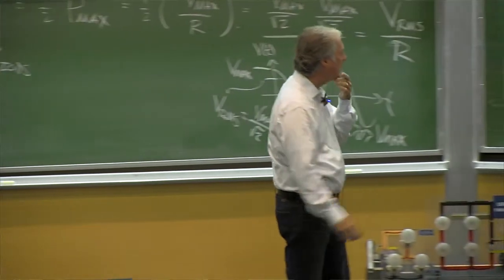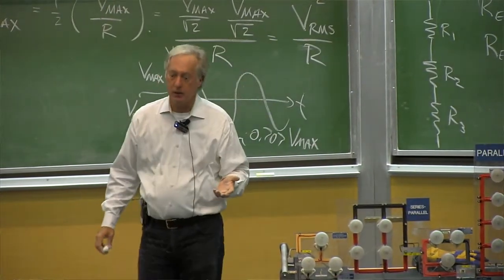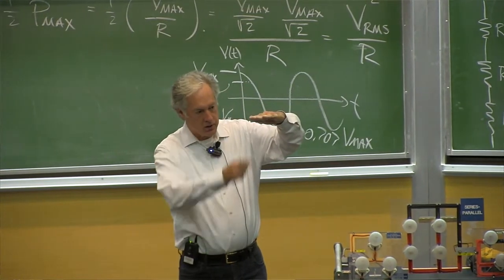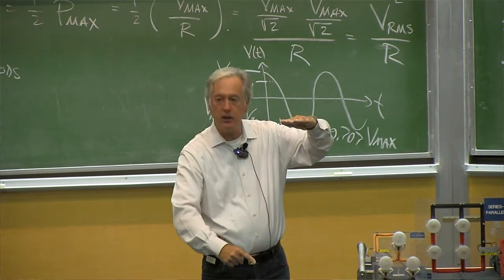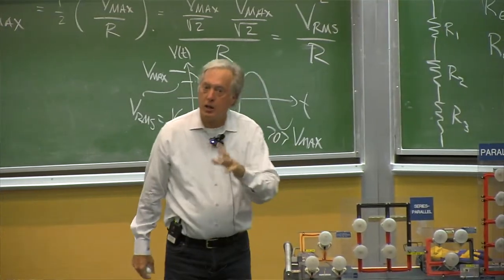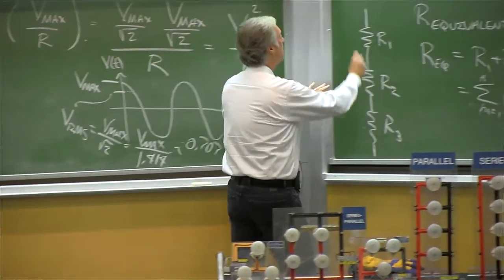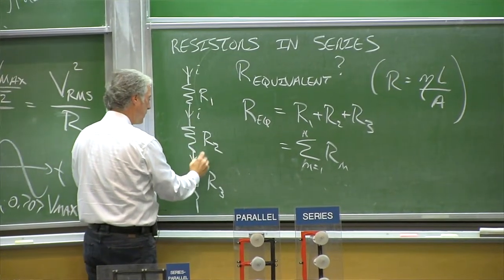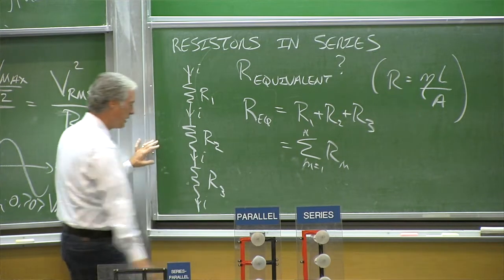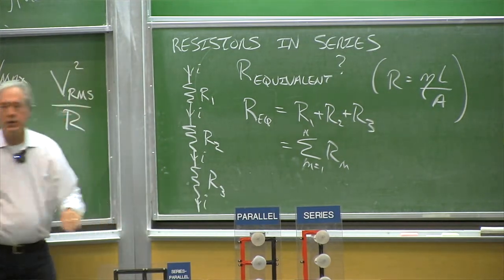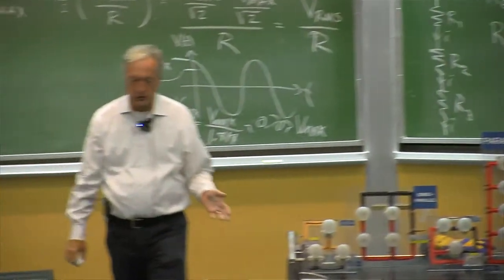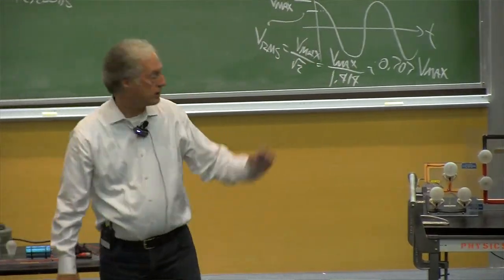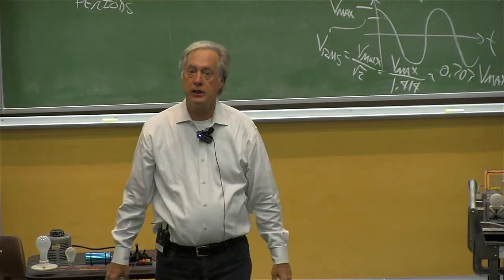Now you can think of it with some math if you want. You can say, the total voltage is here to here to here, and the current that flows comes in. If you put a current in, it's going to go through each one and on out the end. So you know the current, dq dt, is the same through each of them. And then you can write your math equation for going across the voltage totals.